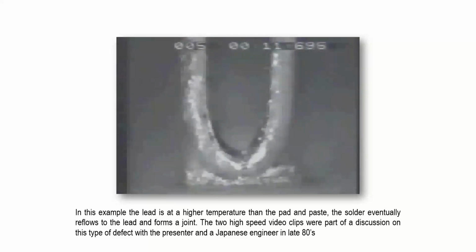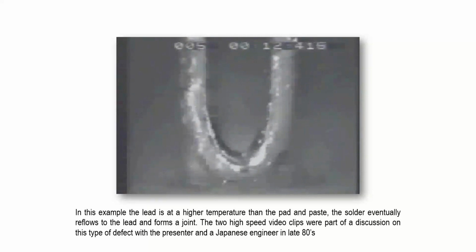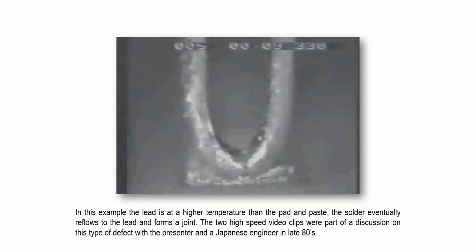In this situation, you can actually see the connector is getting up to temperature and drawing the solder away. You get the same sort of thing if you've got poor wettability or poor solderability of the pad. That's not the case in this particular example, the nickel gold boards the customer is using, I don't believe, but it's just trying to get the solder paste to reflow and wet the pad before the connector and connector pins start to wet. So it's just trying to control the time of wetting on the parts.